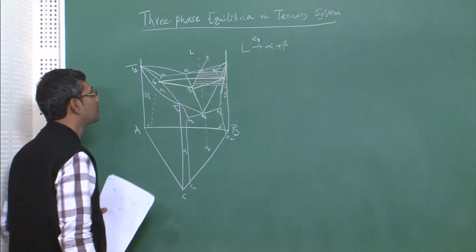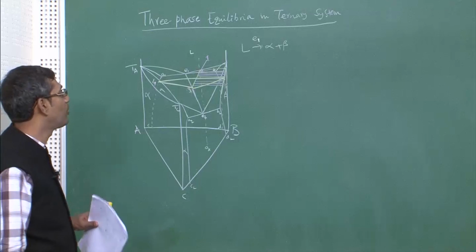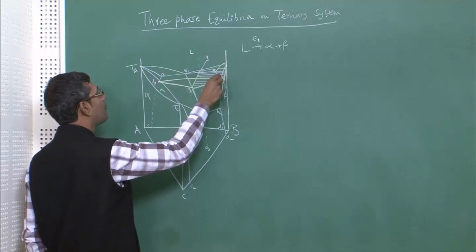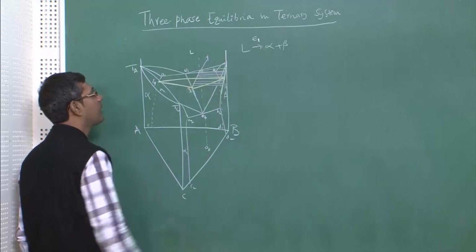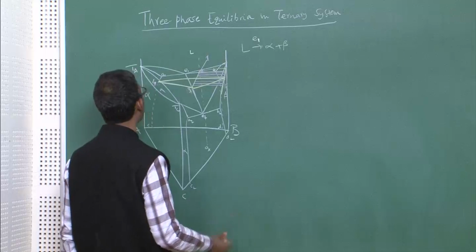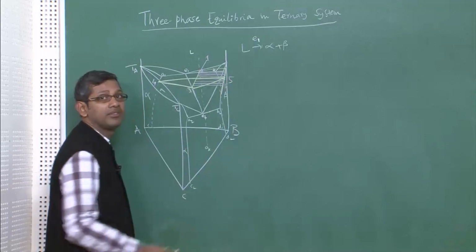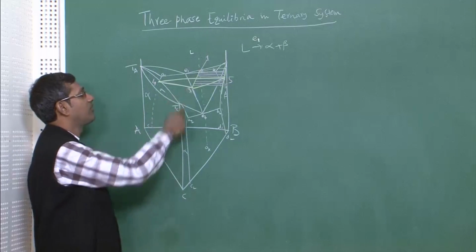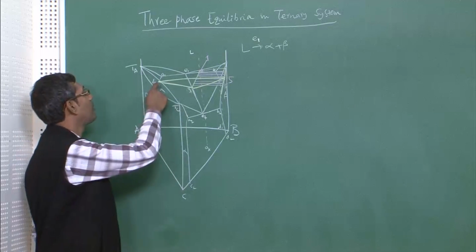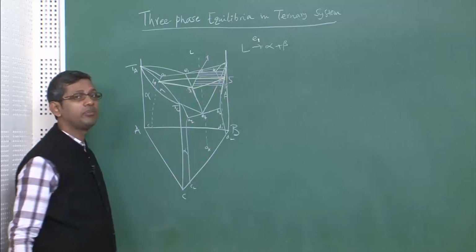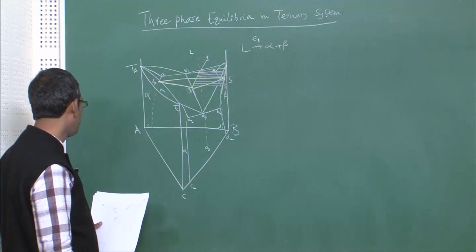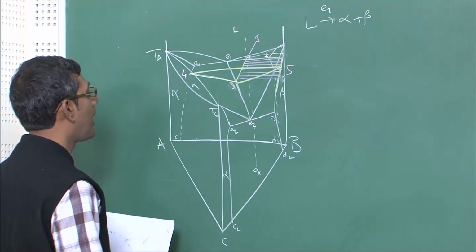Okay. This is a triangle actually which I have been referring you to always. So, the composition of alpha, composition of beta, composition of liquid will be given by these 3 points. One is 0.4, other is 0.5, and the last one is 0.3. 0.3 will tell the liquid composition, 0.4 will tell the alpha composition, 0.5 will tell you the beta composition.